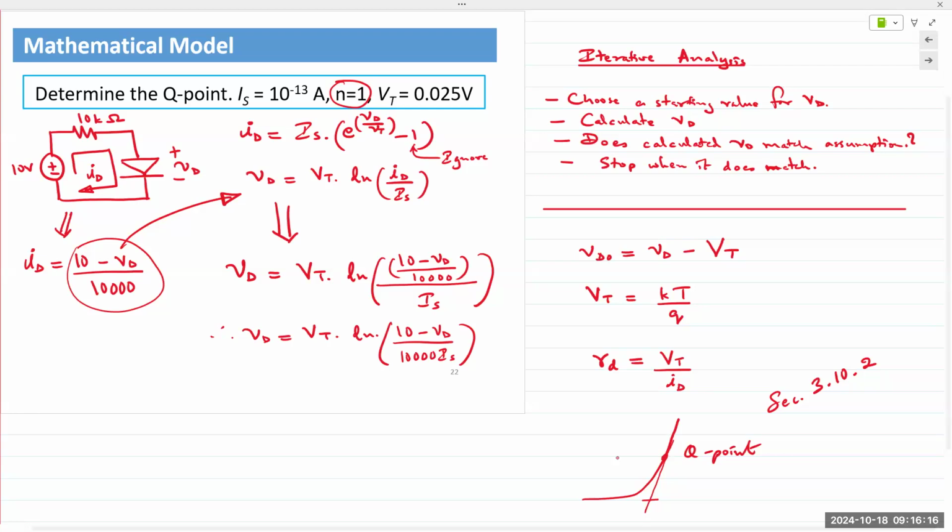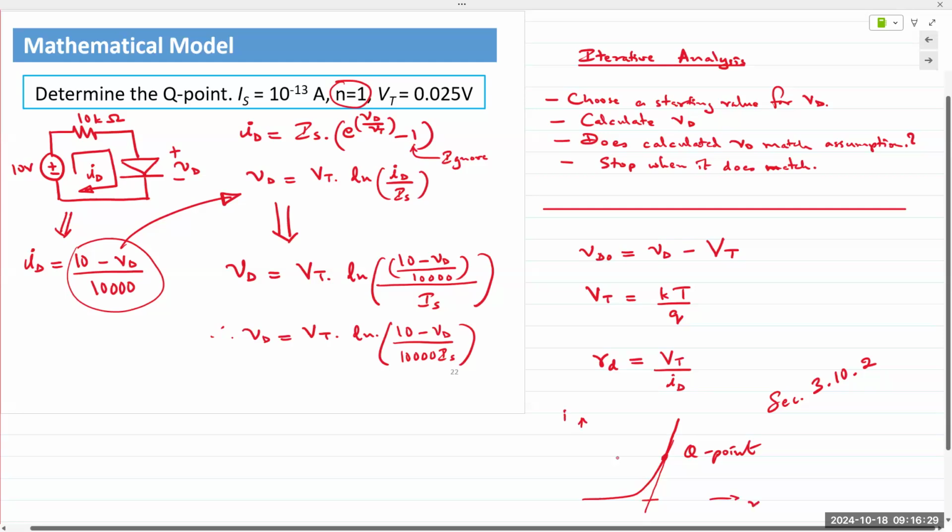And then the slope of that linear line is known as conductance, I over V. This is the characteristic; you have I here and V here. So the slope of this line is I over V, the diode conductance, and the diode resistance is the reciprocal of that conductance. And in mathematical terms, right here, this is R, not V.